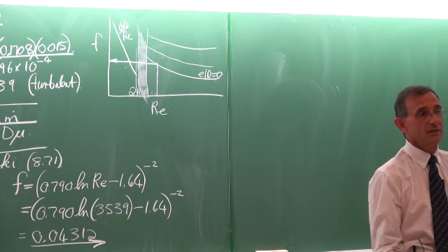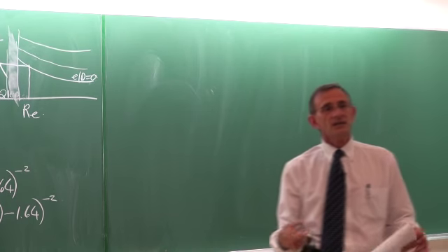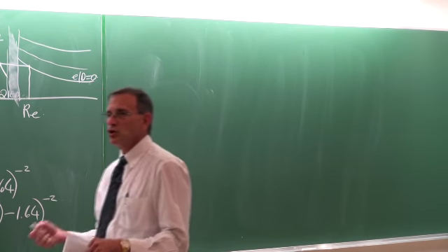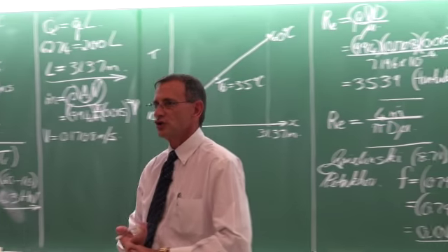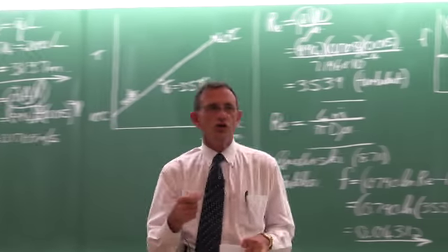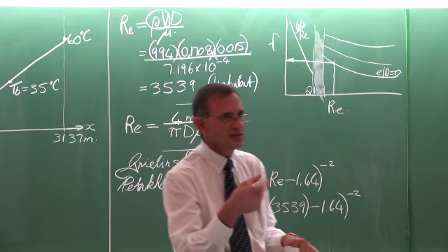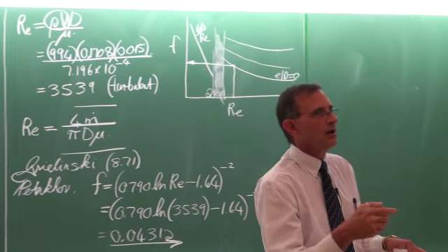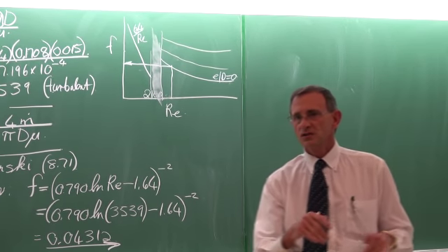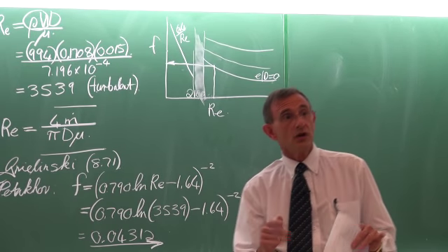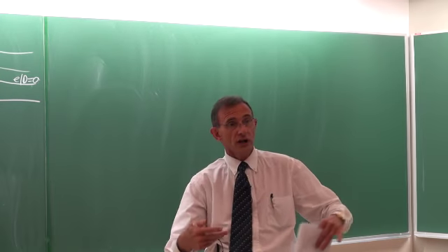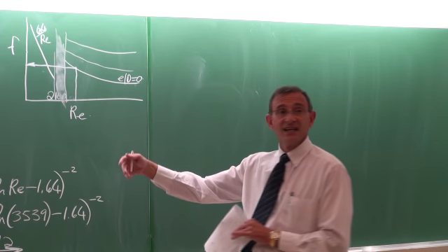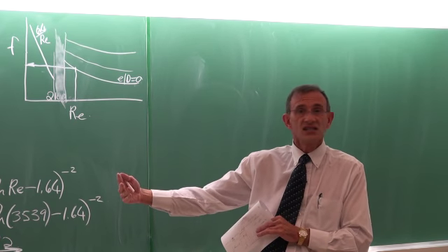Well, firstly, they didn't give me more information, and the second thing is almost all the tubes that you can buy these days, all the hard-drawn tubes, the soft-drawn tubes, if you measure the surface roughness divided by the diameter, I assure you for all practical purposes, they are all smooth tubes. With time, you will get corrosion or erosion, or in this case, scale on the inside.